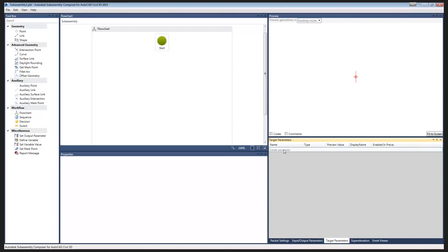Target parameters, you have the ability to target an elevation, an offset, so horizontal distance, or a surface. So we've got three different target parameters. We'll look at those later on. It's a way to, if you're doing a daylighting or a lane assembly, target a width. So when you go into your corridor and into your target parameters, you have the capability of saying, hey, I want my lane to be 12 foot wide, but now with the target parameter, all I do is say target this line, and it will allow the lane to widen to match that line.